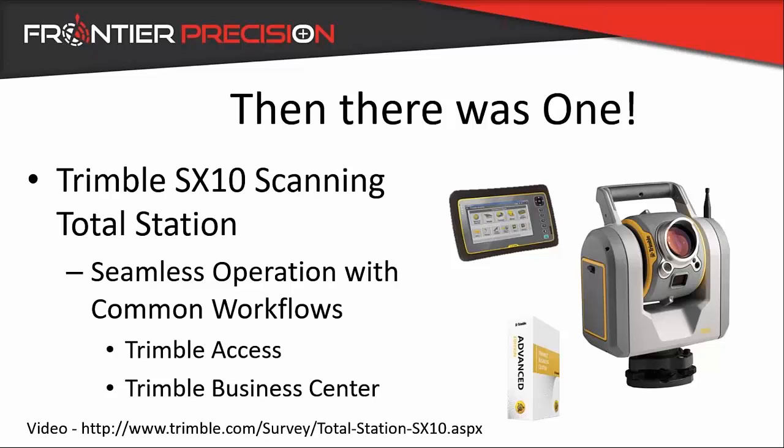How do temperature fluctuations affect the accuracy and the draw of the battery power? So the draw and the battery power are similar to what you would see with a traditional S-Series total station. It operates about 2 to 3 hours on full scan mode on one single battery, or you can run the triple battery holder that comes in the robotic power kit and operate up to 8 hours or so. So it does draw a little bit more than a traditional S-Series total station, and the same effectiveness that you would have with cold weather and things like that will also draw the power a little bit more, just like you would with a S-Series total station.